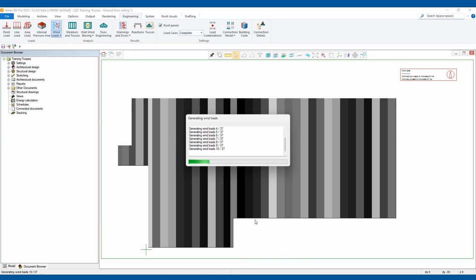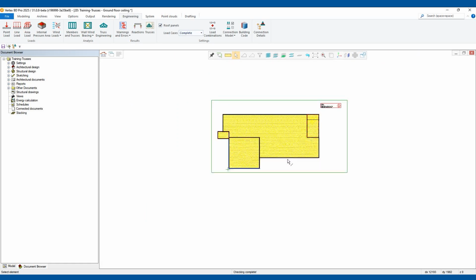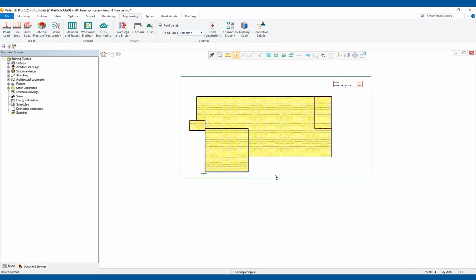And that's going to add our wind loads. Now I must have played in this project before. So normally if this is a brand new project, you'll have an arrow coming up asking for your wind direction. If you don't know the main wind direction, just point it to the long side of the building, that's fine, and that'll be worst case.